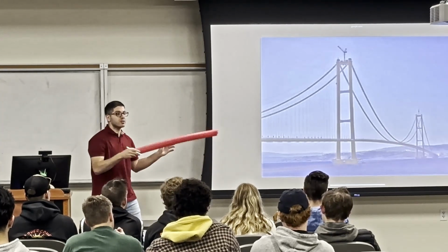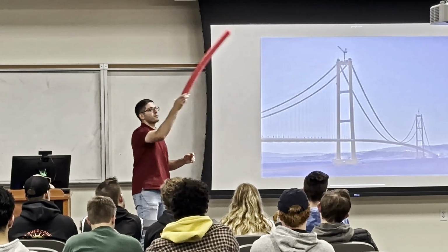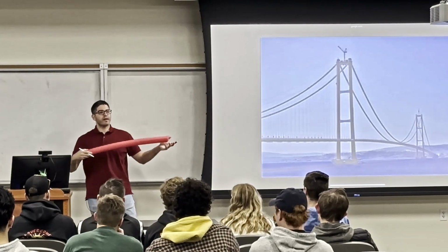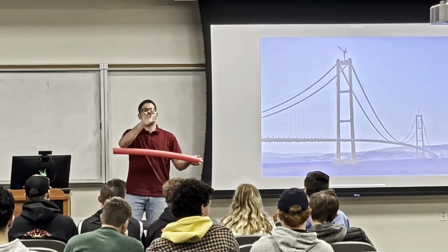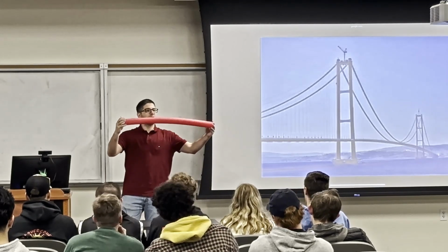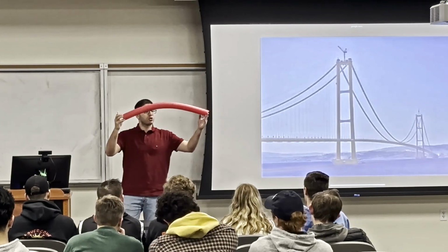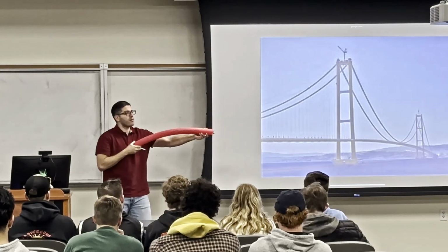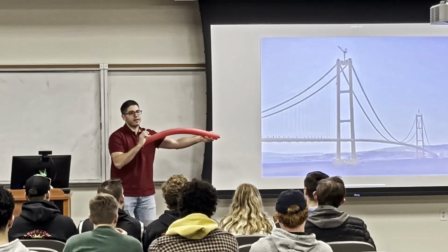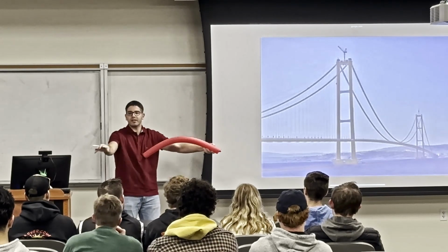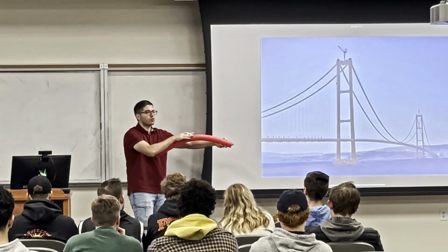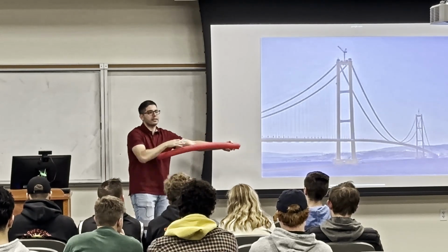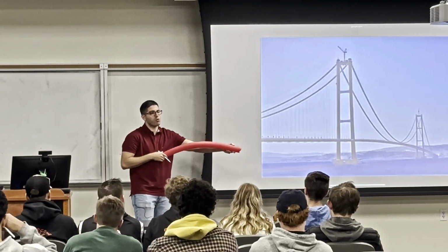And sometimes we do this in buildings. In case of a very long beam, we might pour the concrete in a way that we design the formwork of the beam to be like this. It's not going to be so much, but it's enough, and it's calculated so that when we put the live loads, the shears, for example, and the flooring, it is enough to deflect it to become straight, okay? Because you don't want to walk on a beam that's like this.